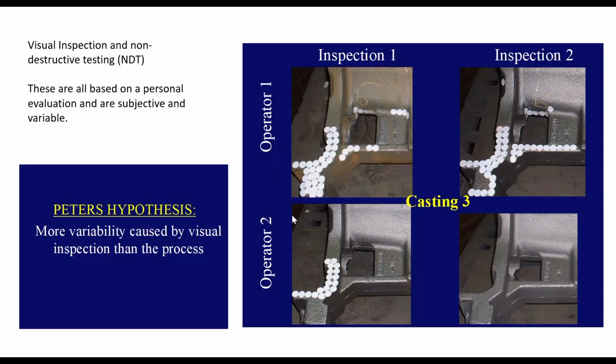And so that's the general reason that we do all of the really additional finishing we do for visual inspection. We found this out pretty early because we were trying to understand why it's difficult to manage the finishing area where we grind and try to complete the surface finish requirement. And when we did that, we found very quickly that one of the biggest challenges is the visual inspection process is not repeatable or reproducible. So here's the same casting evaluated twice by the same inspector and by two different inspectors. And you can see how variable their results are.